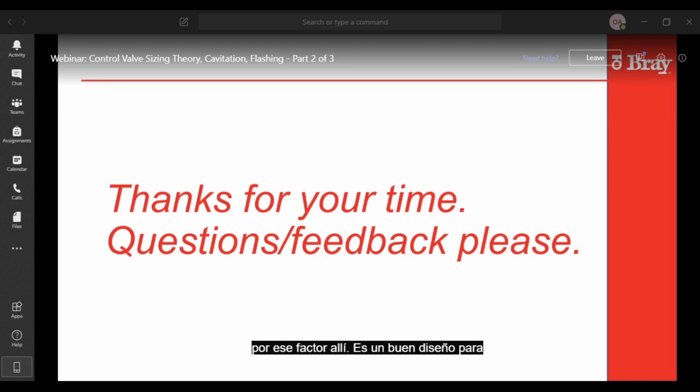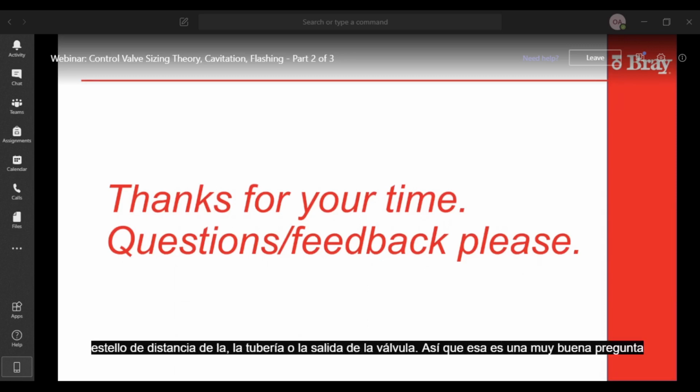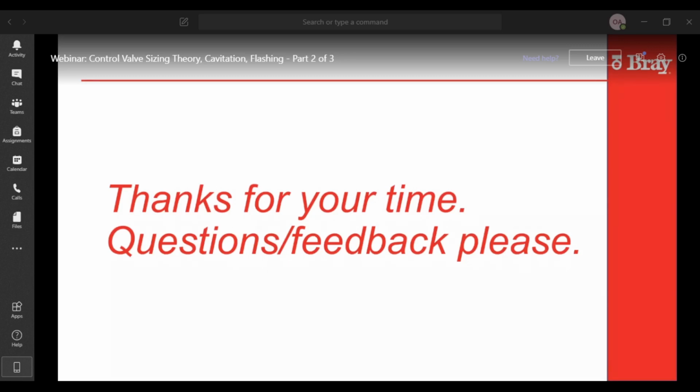Yeah, and that's a good design for flashing, because your flash is going into a much bigger area. So the velocities will be controlled immediately as soon as it gets into that much bigger area. Yeah, so it'll flash really well. Yes, so that's why they put them against the flash tank. Yeah, that makes sense, because then if there are carried over water droplets, they'll try to flash immediately and flash away from the pipe or the outlet of the valve. So that's a very good question, and yes, it would be perfect to do it that way.